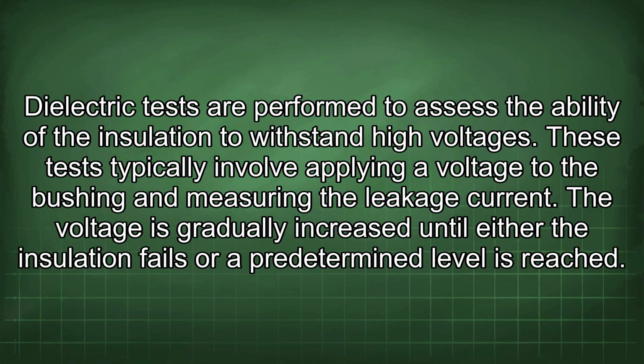Dielectric tests are performed to assess the ability of the insulation to withstand high voltages. These tests typically involve applying a voltage to the bushing and measuring the leakage current. The voltage is gradually increased until either the insulation fails or a predetermined level is reached.